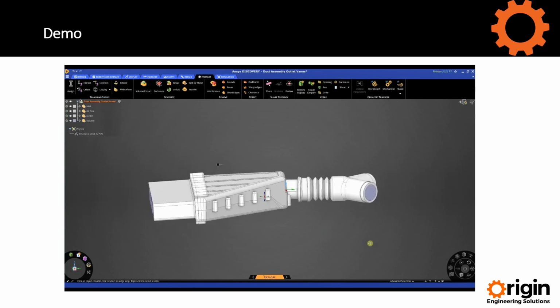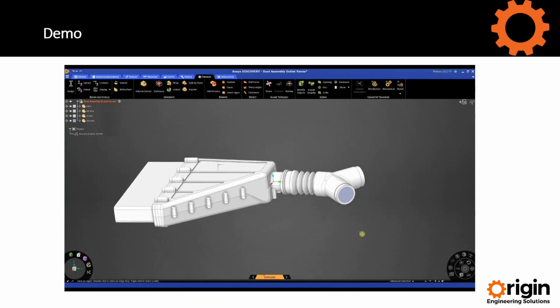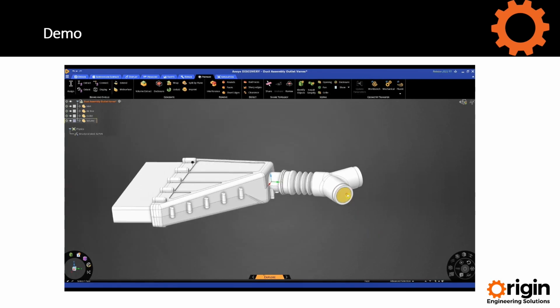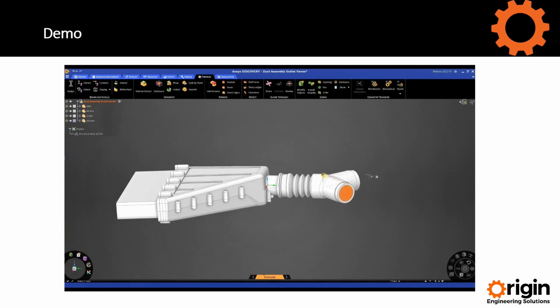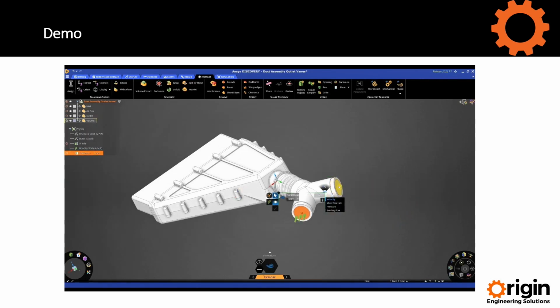The next thing we want to do is actually set up our inlets. So this face and the opposite one are going to both be inlets. I'm going to set up this face as an inlet, and we can specify velocity, mass flow rate, pressure, swirling flow. I'm going to use velocity. I'm going to specify 1 meter per second. I'm going to do the same on the opposite side.